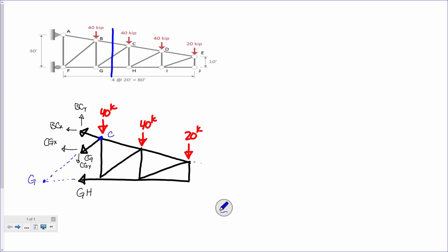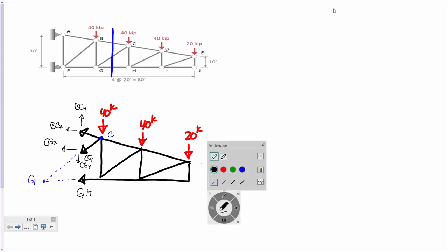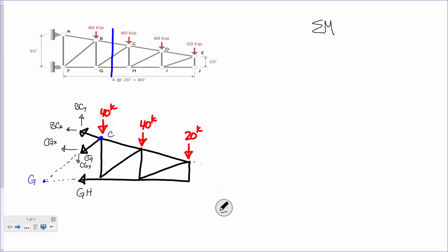Now, for those of you that have had me for a structural engineering or structural analysis class, which I don't think anybody in here has, I sum moments a little differently. This is what I like to do. I say sum of moments about point G equals 0, and then I draw myself a little table. All the moments spinning that way have to equal all the moments spinning the other way. Then, like a bookkeeping operation, I start tabulating them down one at a time. So watch this. I'm summing moments here, looking at this upper truss, right at that little green spot I'm drawing.